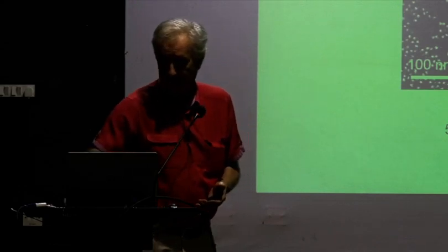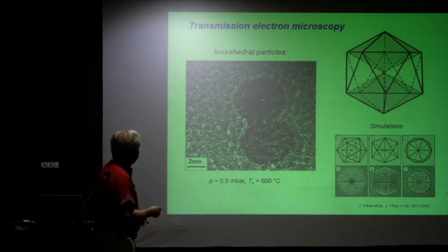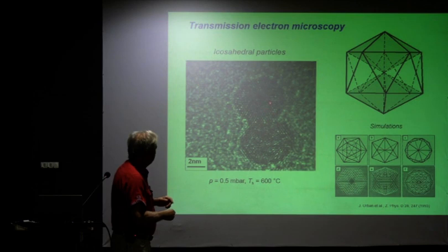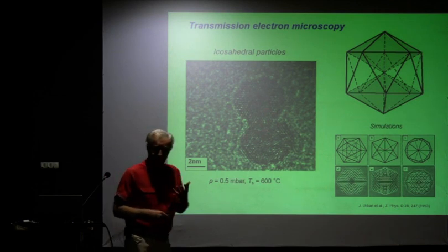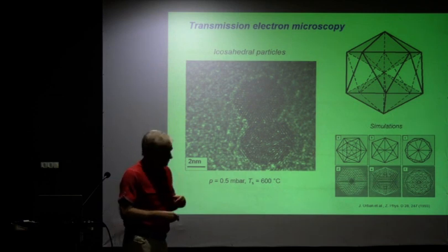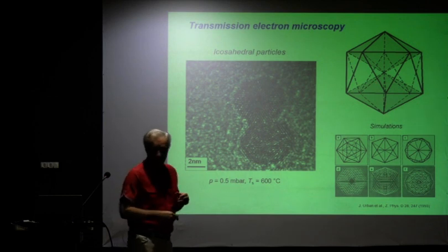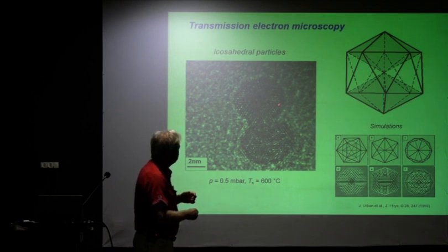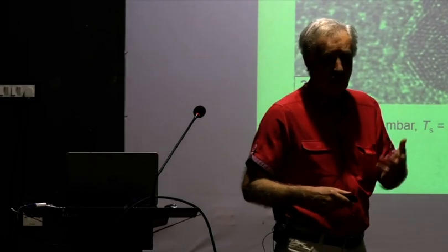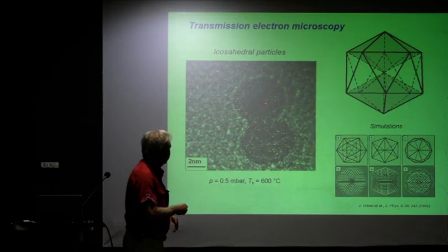higher resolution microscopy and try to understand what we have really gotten. If we look at these things under a transmission microscope, you see that they are faceted somehow. And if you try to understand what these structures are by simulating them with some models, you find that they are icosahedral structures. That is, they have 12 faces. And these faces, they're densely packed, each of them, and they are arranged so that what you have in between are like twinnings, not twin boundaries, so they're twinned particles. They're like the twin boundaries you have in martensite, but of course not martensite. It's just twinned, okay?